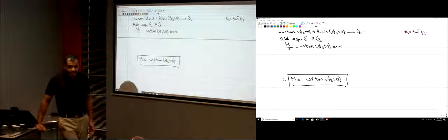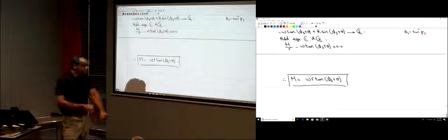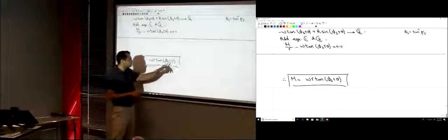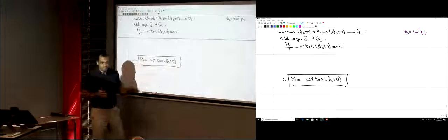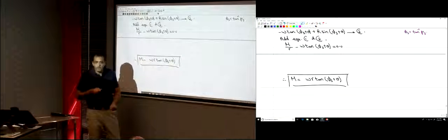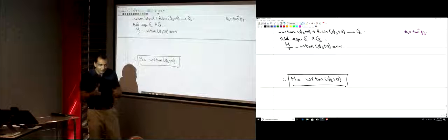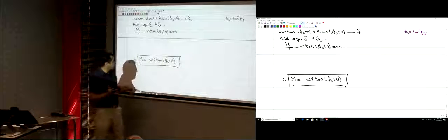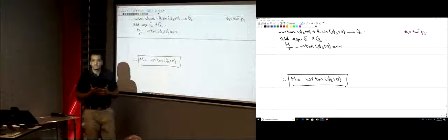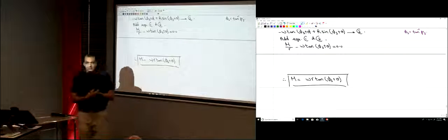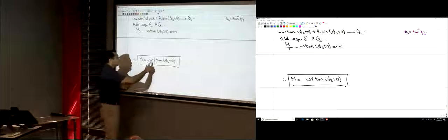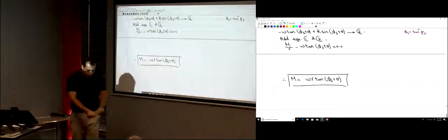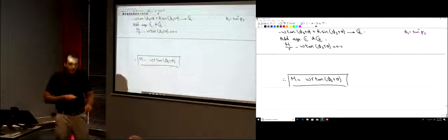We're talking here about the moment having to be large, right? So definitely this guy before you has nothing to do with theta. When he tightened it so hard, he didn't change the angle of the screw, the lead. The radius didn't change. He didn't change the coefficient of friction. The coefficient of friction is a material property. It has nothing to do with this guy. He didn't change R, the radius. He changed W.